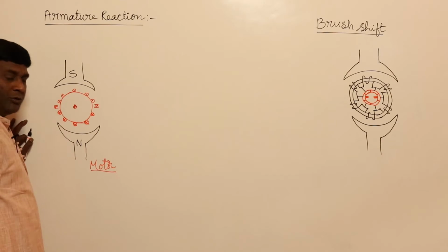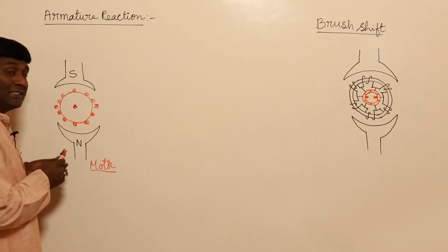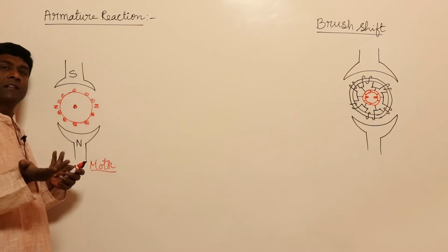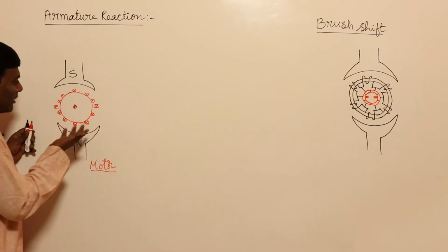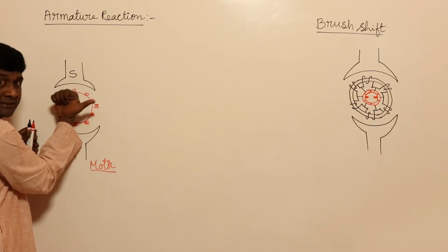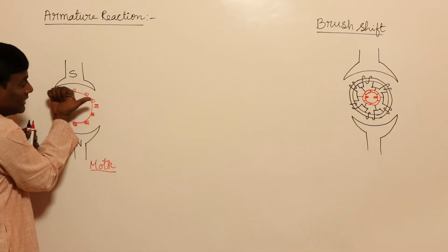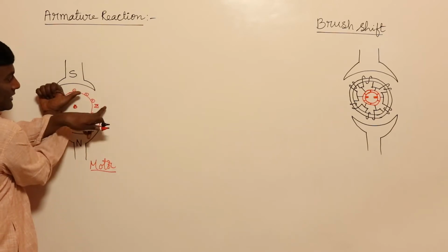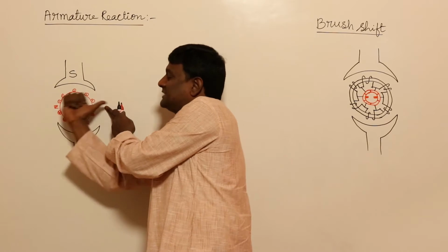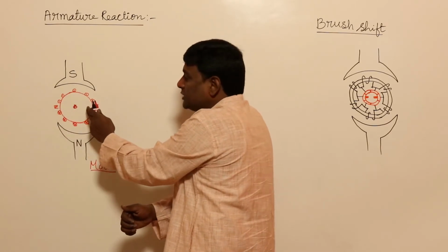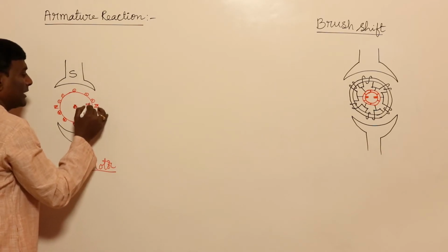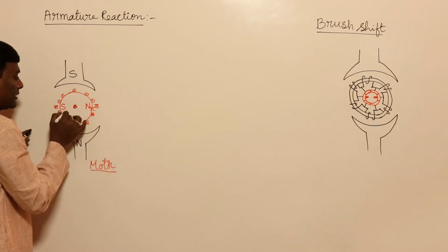If I give it this way, what will happen? These are going to be currents. Whenever current is there, automatically flux will come. Now that flux will be cross here, dot here. So my MMF is directed in this direction. For example, you are sitting in the air gap and flux is coming out of this particular rotor, so this pole should be N pole. So this is going to be the N pole of the rotor, and this the S pole of the rotor.